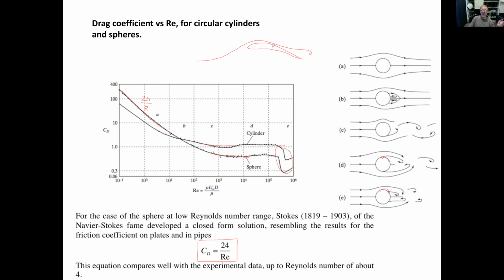So what they're doing, they're putting a vortex generator here, which is going to create turbulent flow. And by creating turbulent flow, this is going to reattach, and you're not going to get that. So it's the same trick as what is happening here. If you make the boundary layer turbulent, then you can delay flow separation.